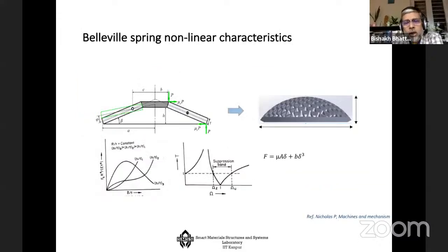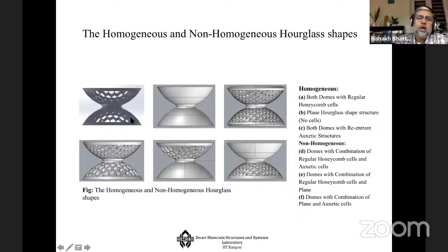But what we have developed is that by developing some kind of auxetic or pattern system inside a lattice, you can actually control the behavior of the lattice. You can control the curvature. So here are different types of auxetic structures. You can see that these are damru-like structures. So something can be homogeneous, something can be honeycomb, something can be reverse honeycomb. You can have all variants of it.